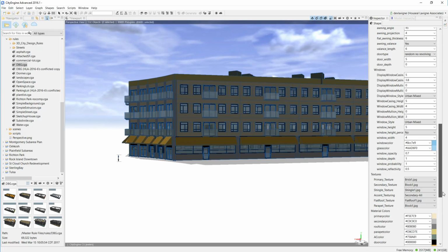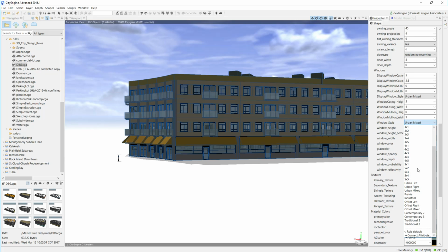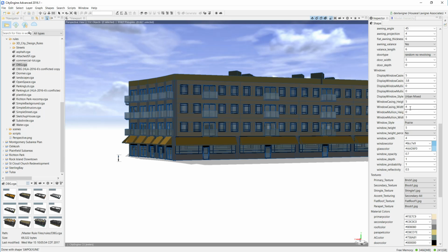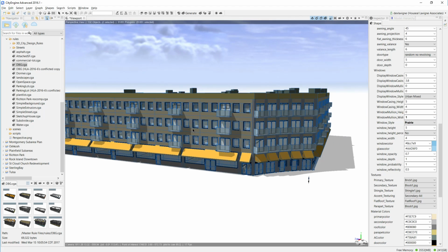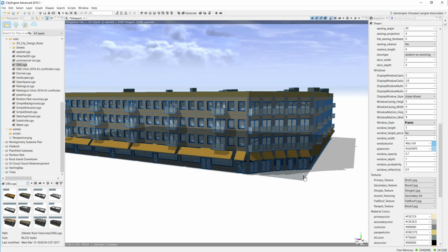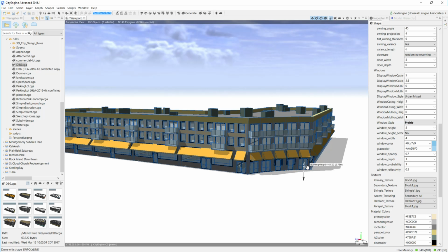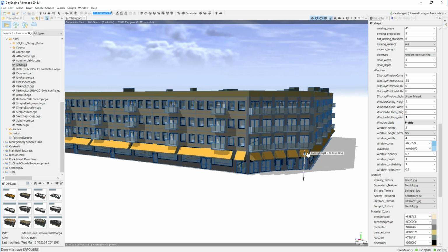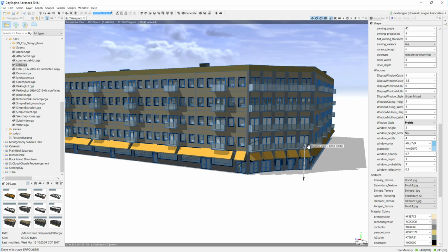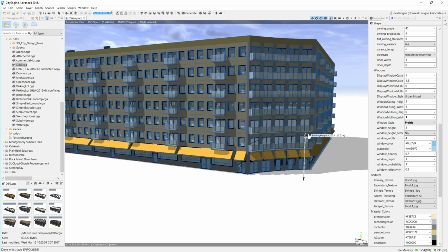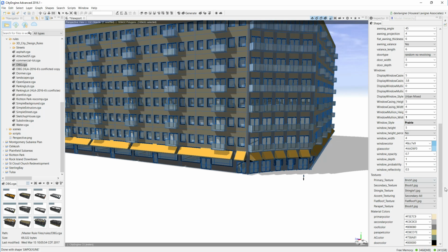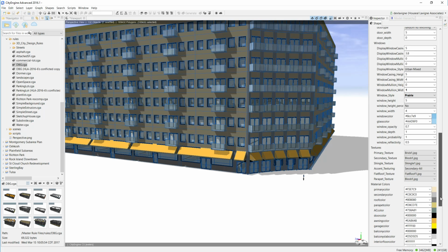The windows are now all procedurally modeled. So this is something I call an urban mix. We can switch that to a prairie style window. We could change the width of the mullion in the window. And one of the newer features in CityEngine, we had handles. So if we wanted to make this a taller building, we can just grab onto a handle and drag it up. And you see the procedural modeling starts to add the detail to every single floor.